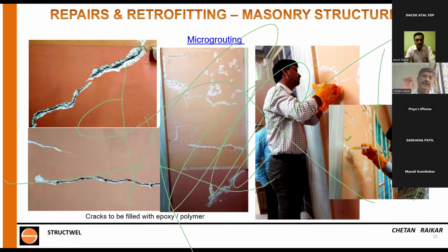It works very effectively and beautifully because it's an epoxy which is as flowing as water. So even if you inject it, it gets absorbed into the material and it flows into the crack up to whatever depth it can. I have not checked actually, but it can easily go to 2 or 3 inches also. So if it's a 15-inch wall or an 18-inch wall, and it is filled on both sides by 3 inches, the trapped air in between, even if it heats and expands and contracts, will not have enough expansion and contraction force to put pressure and make the crack reappear.